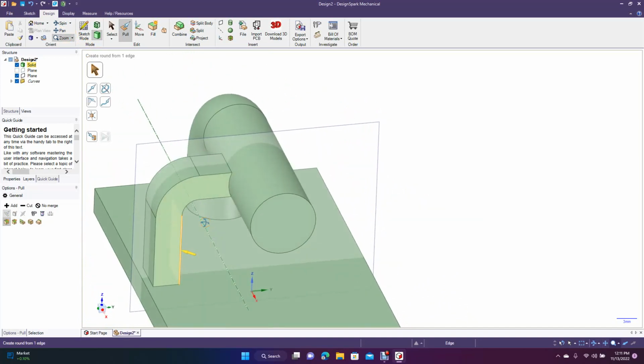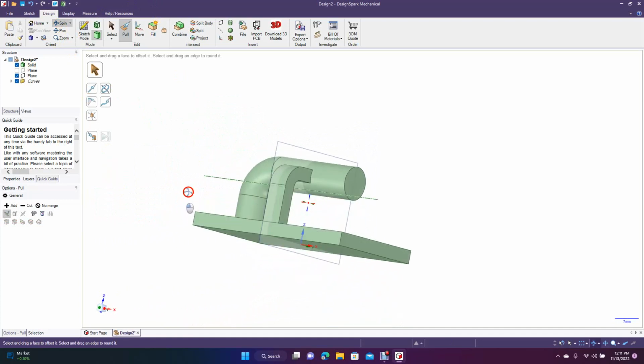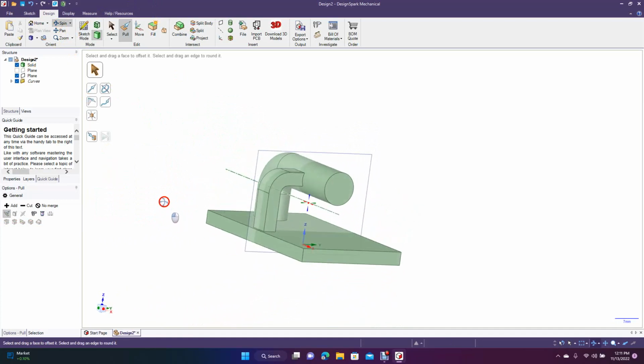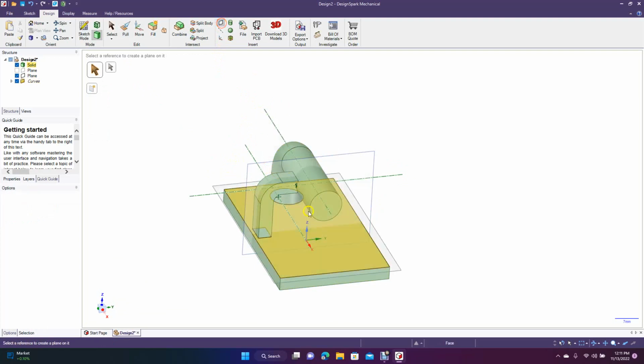Let's press Control minus to zoom out a little bit. Then we'll go ahead and spin this. Basically anywhere you put the plane, if planes are confusing, just think of this, like I said earlier, as a wall. Then think of the plane's direction as the direction in which you can draw your path. If we wanted a path to go this way, we'd have to put a plane this way, in the direction that we want the profile to go.